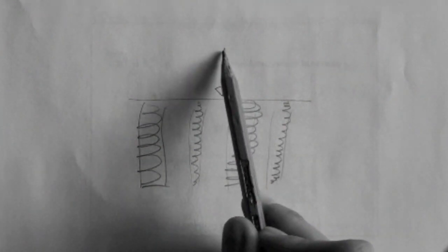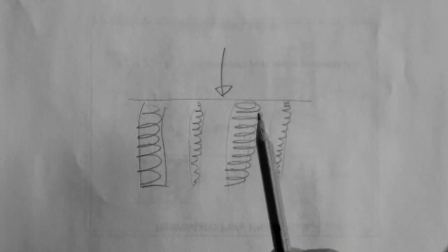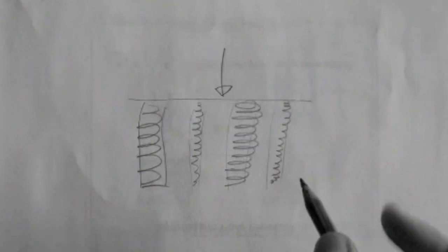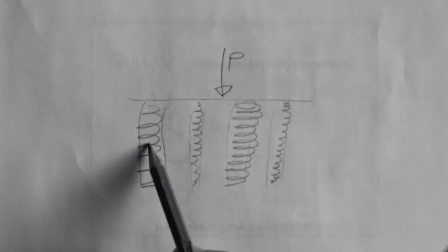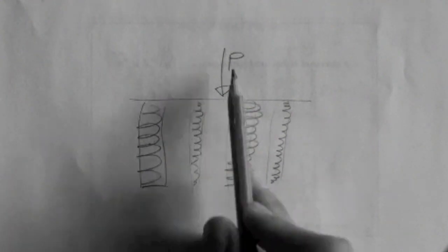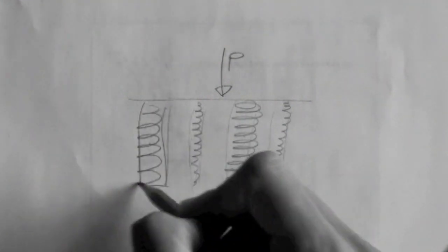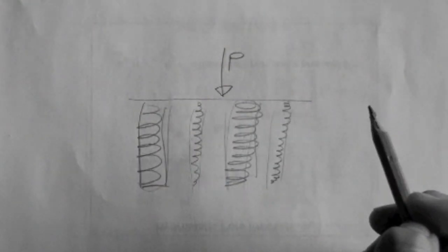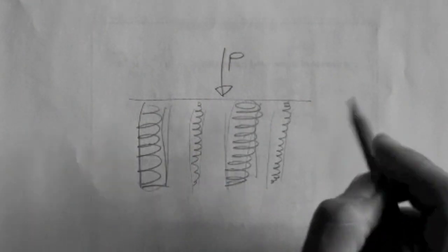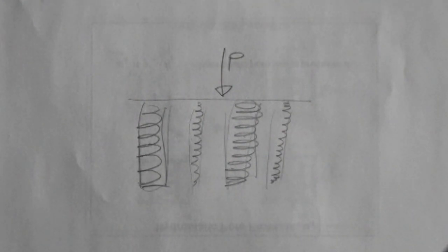Do you think these four springs carry 1/4 of this force? This force is P. Do you think this spring carries a fourth of P, this one a fourth of P, this one a fourth of P, and this one a fourth of P? No. The springs that are stiffest carry most of the load. Okay? And so that is something that applies to all materials. If there is a system of materials together that make a composite material like soil, and there is a load applied, then the component that has the highest stiffness will carry the load initially.